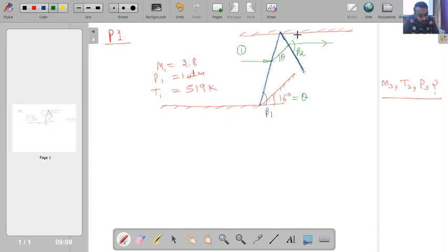And this particular direction and the new direction of the streamline, whatever angle these make, will once again be theta. Is this one clear? So the earlier direction of the streamline and the shock wave make the beta 2 angle, and the streamline between its earlier, extended direction and its new direction makes an angle theta.